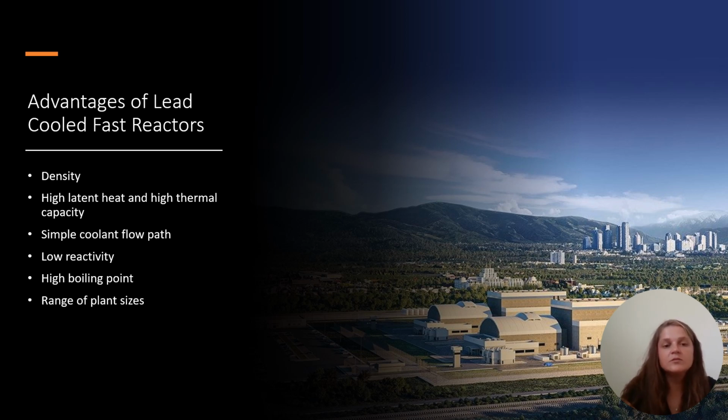Lead does not react with either water or air, so in the event of a leakage, there will not be rapid chemical reactions like there would be with the sodium-cooled. Lead also has a high boiling point that allows the reactor operation at or near atmospheric pressure and eliminates the risk of core voiding due to coolant boiling. This also leads to higher safety margins and the ability to operate at higher temperatures.